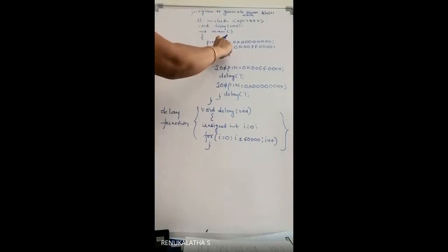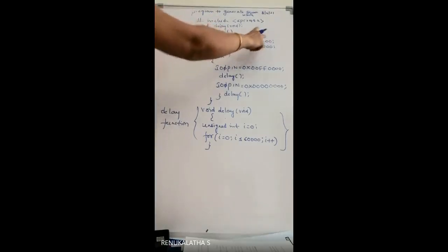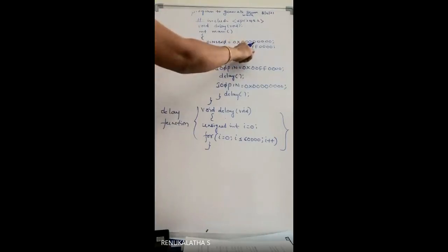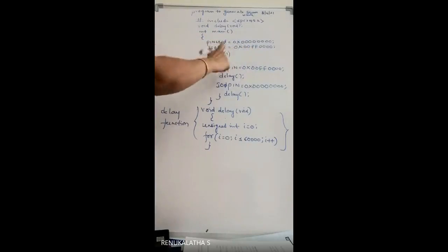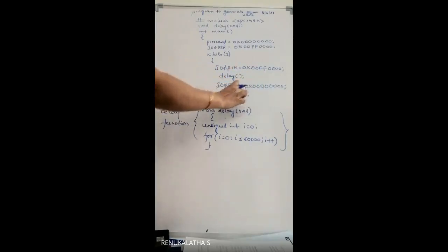So then this is the initialization. Pin select 0 should be all zeros because of GPIO mode, and direction of 16 to 23 should be fixed as outgoing pins, and enter the loop. Then you pass ones for a certain interval of time, and then you pass zeros for a certain interval of time. Then you complete the delay subroutine. Did you follow this?